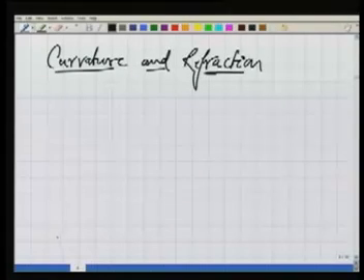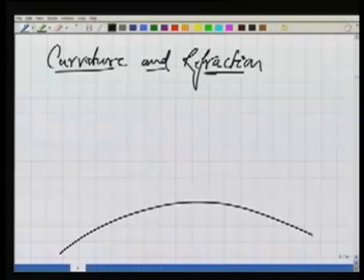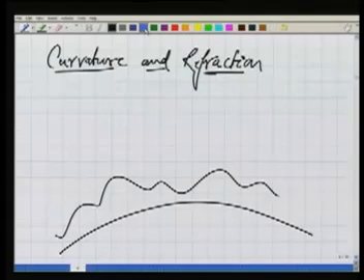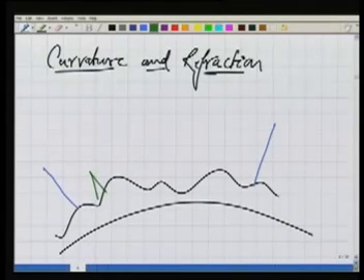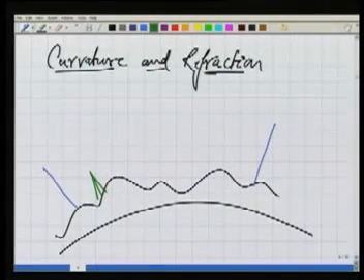That is my datum, the mean sea level, and somewhere here is my terrain. Over here I am keeping my staff, and another staff is kept here, vertical, and somewhere here is my instrument. We know that when we take the observation, the instrument tries to establish a horizontal line of sight.